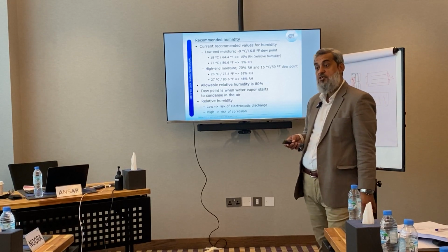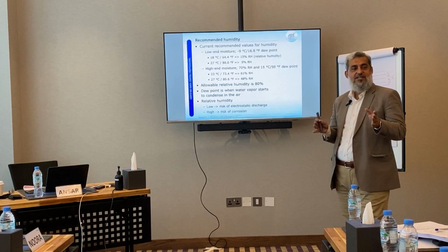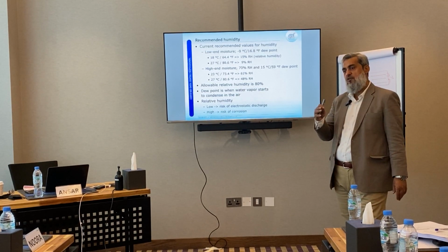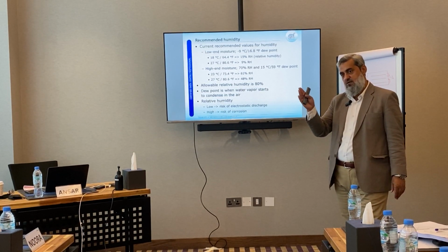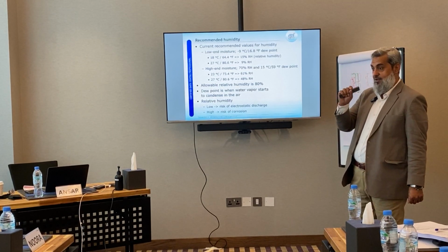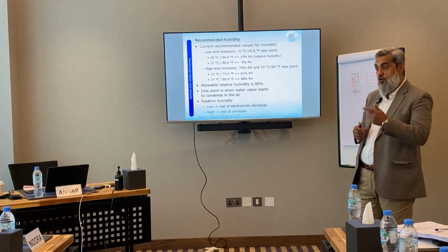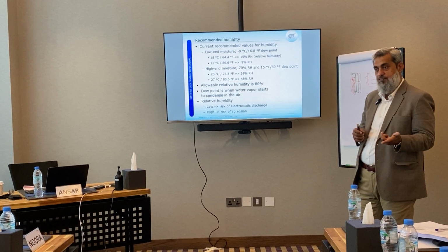So you need to know the dew point of your data center. The typical range of the humidity is around 45 to 80%. Recommended is to keep it around 55%. But understanding the dew point is important. So how do you know what is the dew point for your data center?